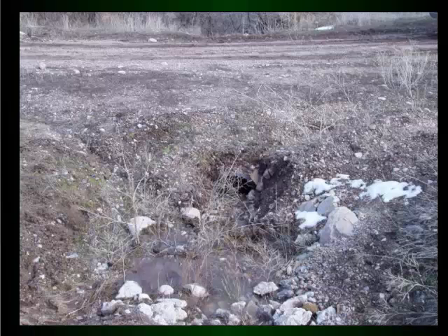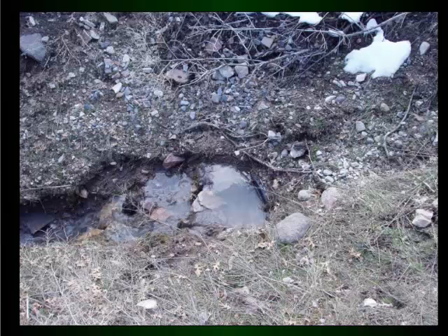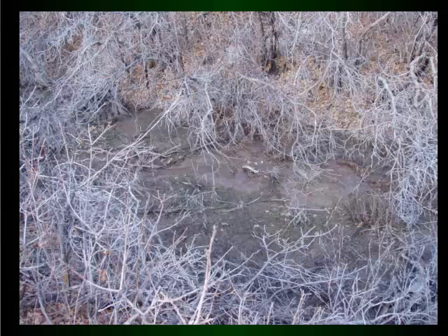This is a culvert here. You can see that it wasn't long enough to stick out, and it looks like someone's been in there and cleaned it out, but since the pipe's too short, once again, it might be a seasonal activity that could be avoided if the pipe was longer. This is the outlet side, and you can see that it's pretty well buried. There's enough debris down in here that's actually up to the top of the pipe level and causing it to back up. And that's just a sediment deposit that came through a pipe.